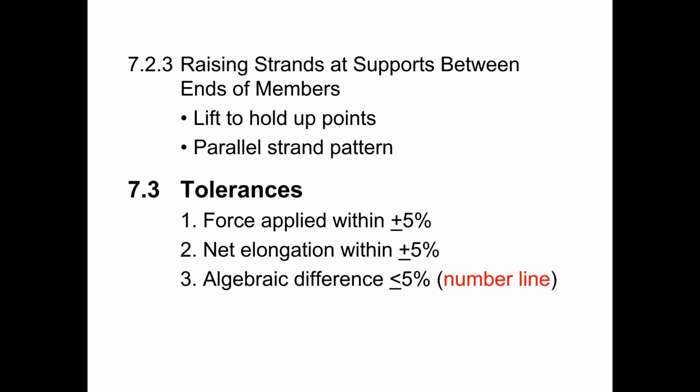And so as it corrodes, then the rollers may not work as well as they should. And so we want to keep an eye on those hold-up points, make sure that they're inspected, that they're in good working order, so that we don't have any safety issues, and also so that we don't have any tensioning tolerance issues.